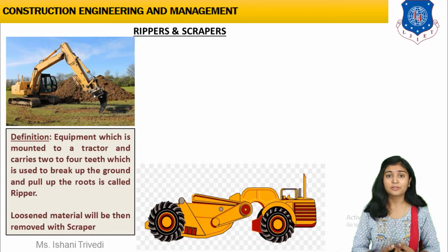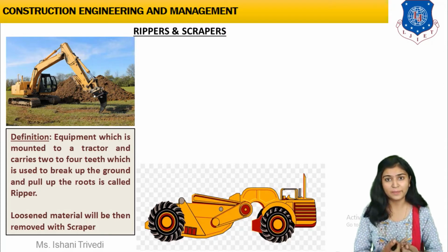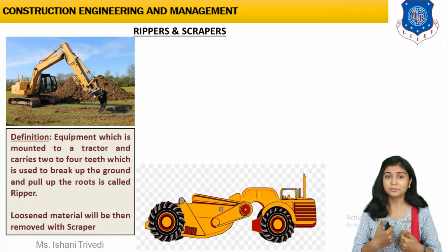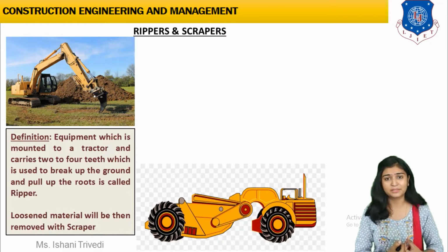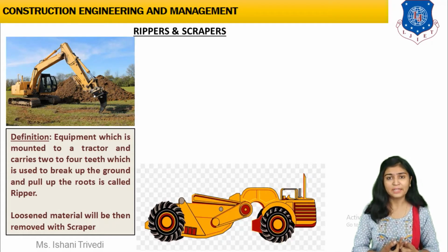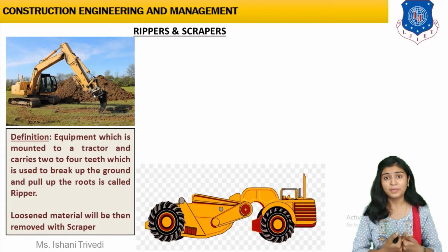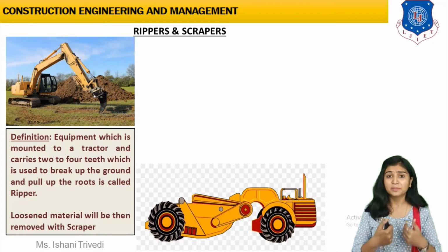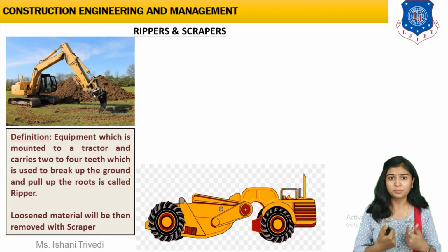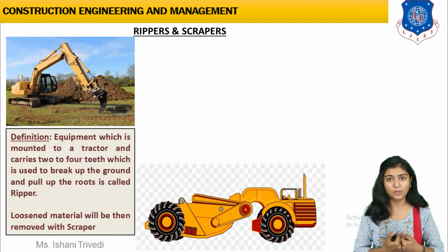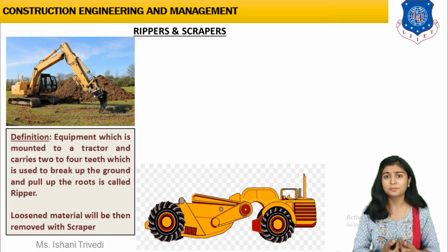So for that you will have to excavate the area, you will have to move the earth, you will have to move the soil. And if you are dealing with the type of soil where boulders are present, where rocks are present, where gravel is present, then your simple excavator, your simple power shovel is not going to break it. Instead of that you will have to use the equipment called rippers, right? Rippers are used for ripping the rocks present inside the soil. Ultimately you are excavating the soil, nothing else is very big over here.